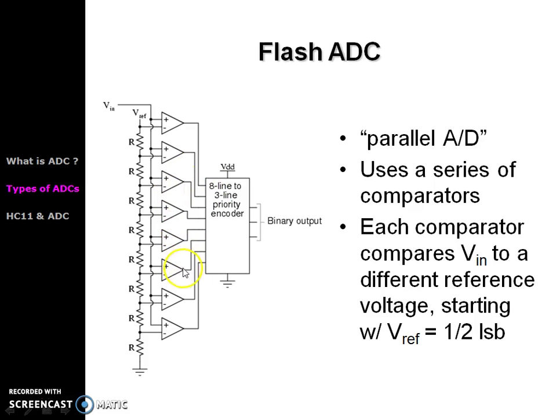Previously all the states are equal to 0, and when Vin is applied, only a few states change; based upon the value of the input voltage, one comparator may be on, or 2, or like that. All 8 comparators can be on, or a combination, with a few on and a few off. Now different values of inputs are applied to the priority encoder.